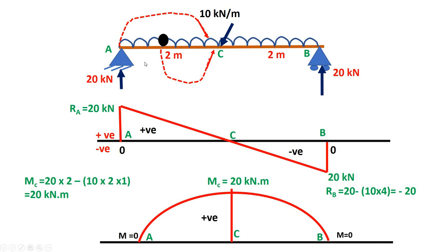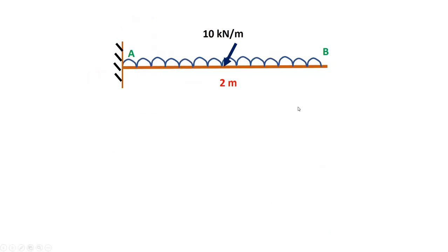Now next, a cantilever beam, right? Here how will it deflect? It will be like this, right? So what about the moment generated over here at the fixed support? The moment is clockwise and the resistive moment will be anti-clockwise.